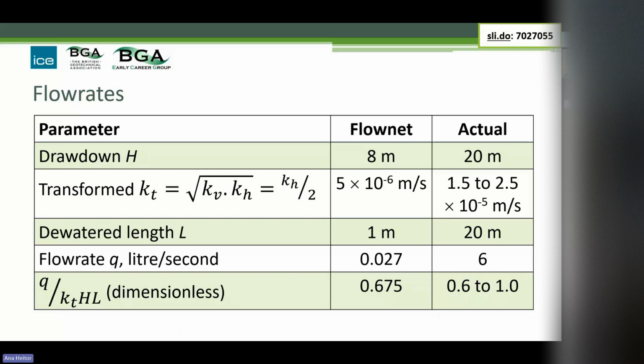It has forced us to think about where is the flow coming from, where is the flow going to, what are the bounding flow lines, and we can get quite a good visualization of what the flow looks like. Even if you then run it through a seepage program or a finite element program, if it's not giving you an answer which is something like your flow net, then there's probably something wrong with the way you've set up the program.